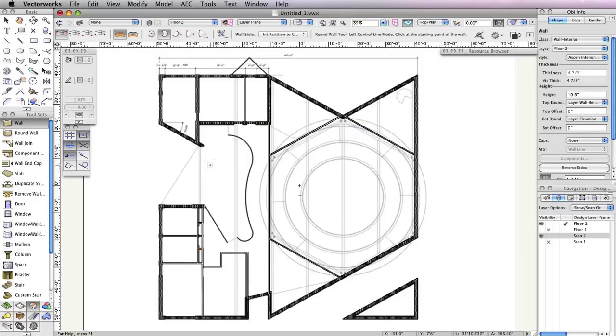As you're tracing the walls, press the U key to cycle through the wall alignment modes in the toolbar to make tracing easier. Additionally, don't forget to use the Snap loop to get a closer view when necessary. Here's what you should have once you're done.